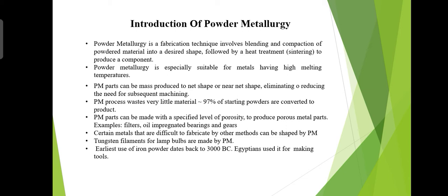Powder metallurgy has several advantages over normal alloying processes. Dissimilar metals that would normally segregate due to differences in density or melting point can be forced to alloy, and additional metals that do not bond can be cut into the matrix and influence the bulk properties of the material.